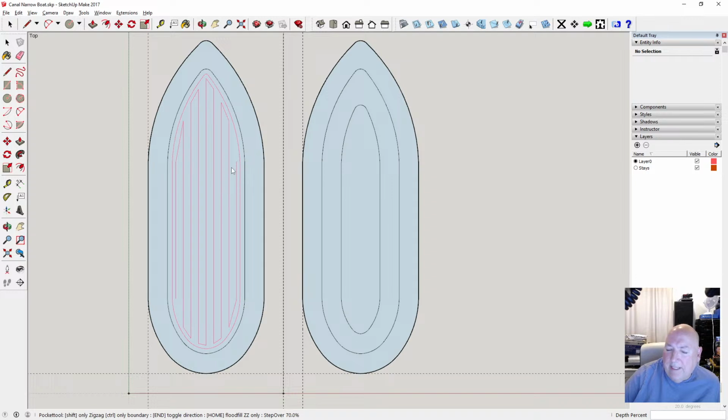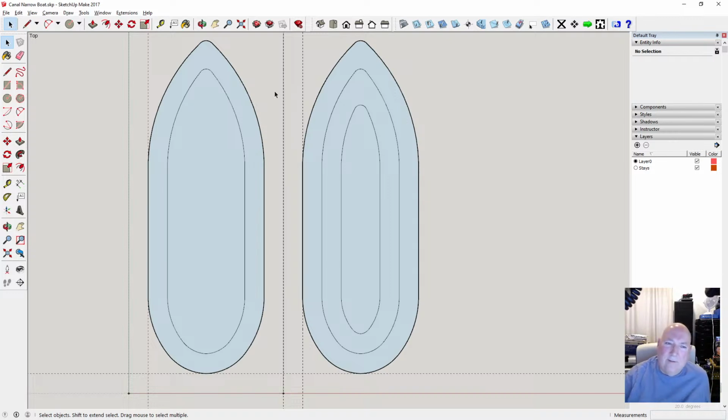Now we need to give it a percentage of depth. It doesn't do millimetre, it does a percent. So I'm going to press escape. So what I need to do is I'm going to be using the 20mm thick wood. It looks the better stuff, and I need to keep 2 or 3mm. The CNC bed isn't exactly flat, because of that fact, and because you can't clamp your wood flat easily,